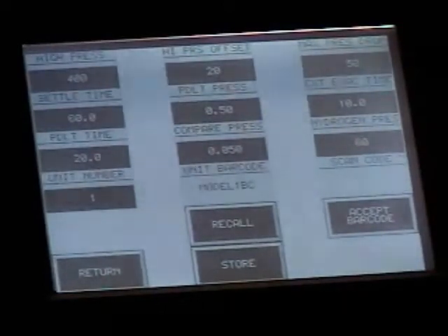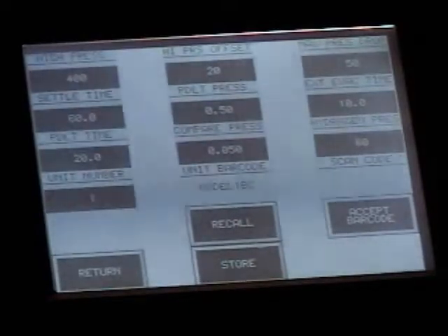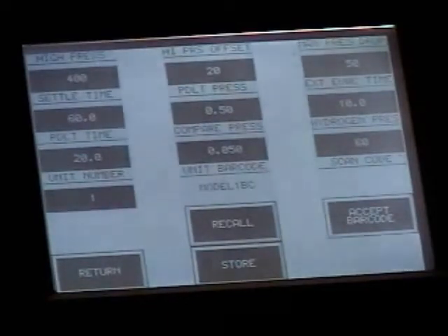If the pressure drop exceeds a half a pound, the unit is deemed to fail. These presets were predetermined manually using pressure and time, and these were found to be stable readings for those units in the manual profiling test.